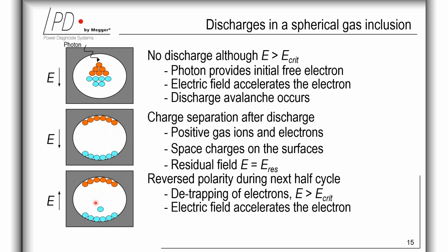But this, which we call the detrapping mechanism, has its own material-related time constant. And also there is statistical variation, since the thermal movement of the trapped electron also superimposes the bond energy, and that means that it modulates the energy needed for detrapping.